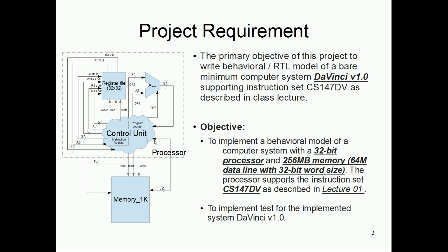The main thing you need to do is to implement a register file, which is very similar to the memory modeling that has been done. For the ALU, we take it from project 1 and extend it to have a zero flag as an output. The main part, the fun part, is implementing the control unit.